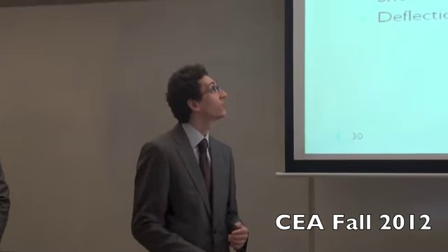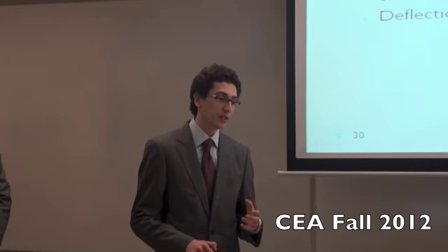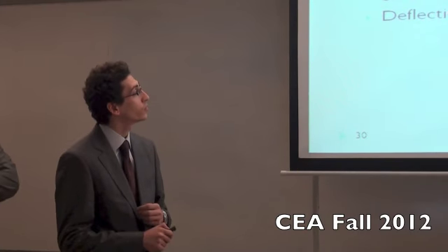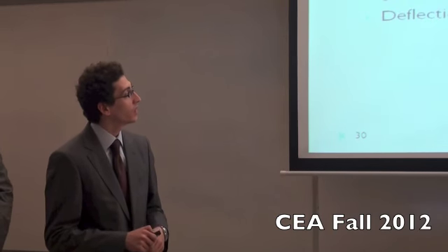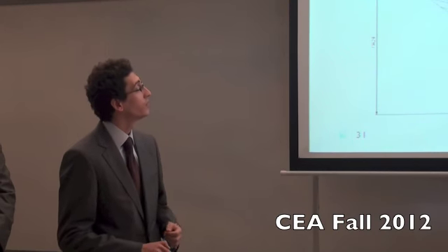The aim of this study was to choose the optimum angle of inclination that would create minimum stresses all along our pylon, and this was the criteria for selection and comparison of the different angles, which are the moment, the shear, and the deflection. We created 7 different models.